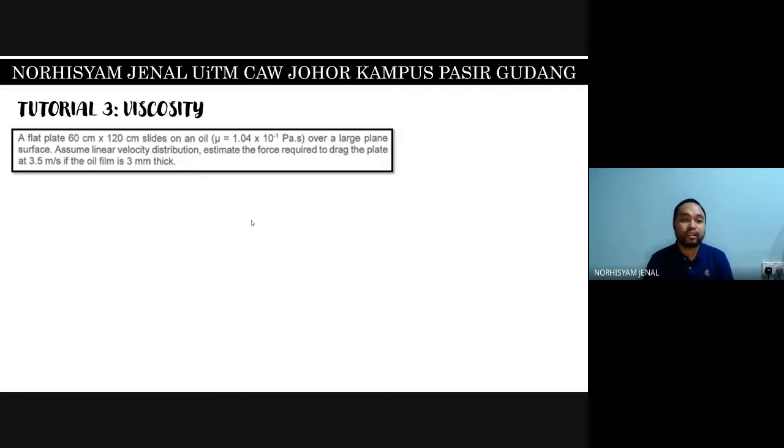A flat plate 60 cm times 120 cm slides on an oil over a large plane surface. The dynamic viscosity is provided here, 1.04 times 10 to the power of -1 Pascal second. Assume linear velocity distribution. Estimate the force required to drag the plate at 3.5 meter per second if the oil film is 3 millimeter thick.